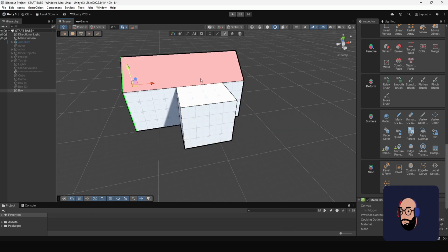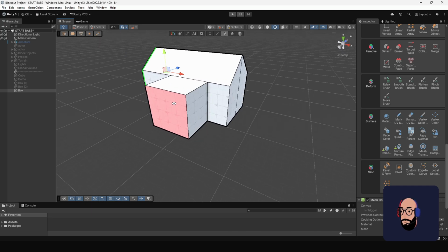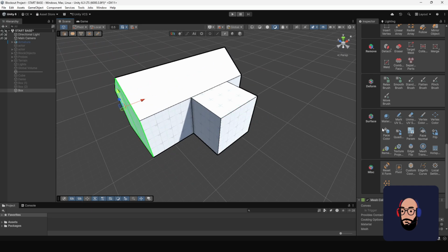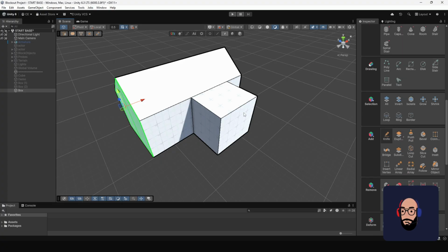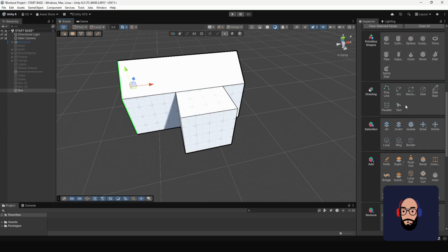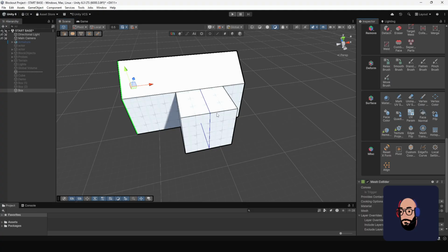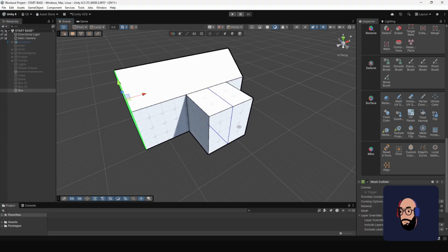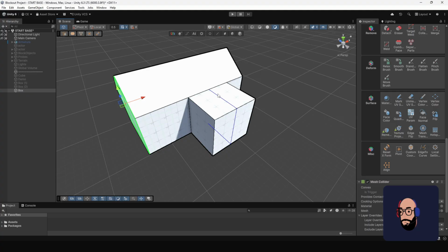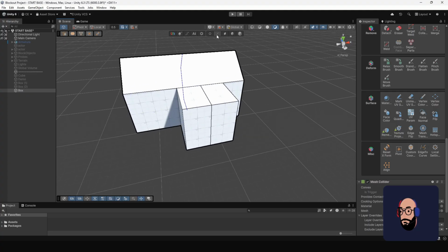We want this roof to also go up. So there's a couple ways to do it. We can try a couple different tools to approach it. Now what we can do is try to use the loop tool. So that's one way to go about it. We can just use the loop tool, and as you can see, it kind of creates a loop just for this part. If I click, that does work properly.